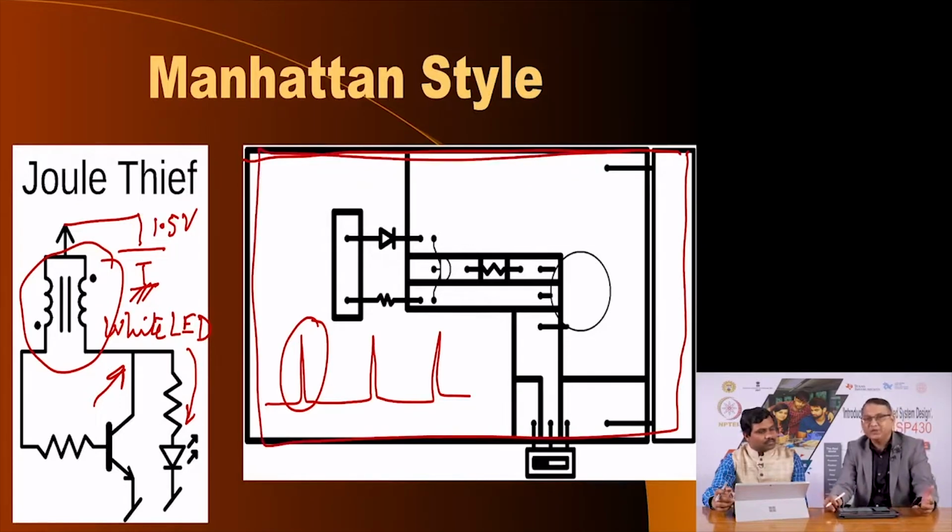Actually, it is not the PCB, it is a raw copper clad board, meaning the board that you would get in the market with the substrate of various sorts pasted with a very thin sheet of copper. Typically, the thickness of the copper that is pasted on substrates is roughly 35 micron, and this is the raw form of the copper clad board that you would get.